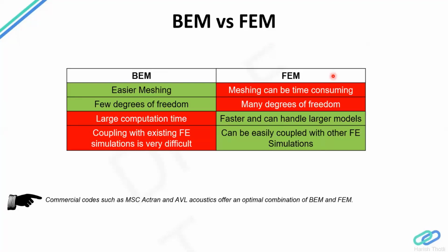You can imagine how it could be with a 3D mesh. And when you are meshing your acoustic mesh, especially the fluid mesh, you should be really careful to avoid any triangles. So no tria elements in the acoustic fluid mesh. These are deep technical details, but we can continue.